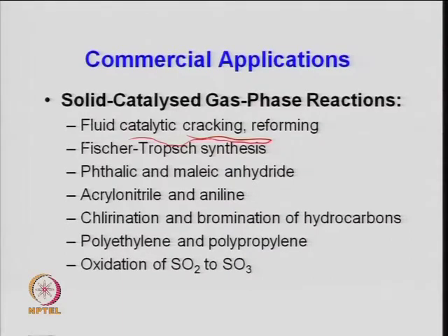Then reforming, platforming, which I was talking about, is done in this kind of reactor. Different kinds of semi-regenerative processes or continuous regeneration of the catalyst are possible with this kind of operation. A moving bed reactor was used earlier, and now it is being replaced by continuous reforming using a fluidized bed reactor system.